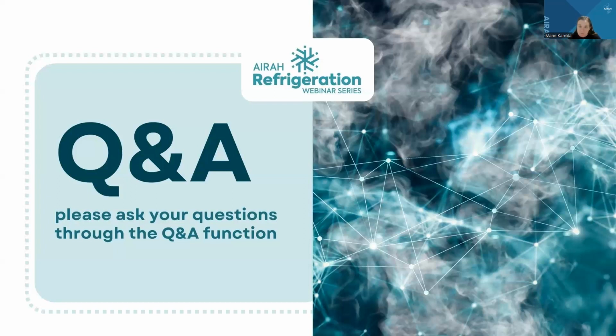Often you have multiple evaporators in the room, at least in a large room, so they're not all defrosted at the same time. So one might be defrosting and others are still operating. Obviously the one defrosting will be imposing a heat load on the other operating evaporators. Yeah, so it's more the case, because otherwise the room temperature goes up and out of spec. Whether it's desirable for the product is another thing.